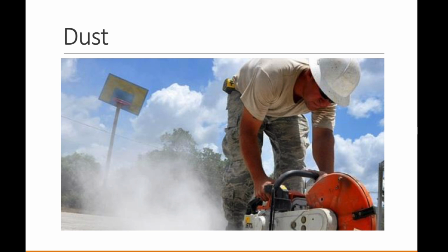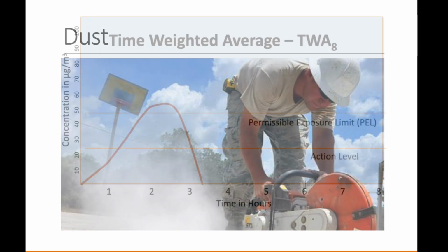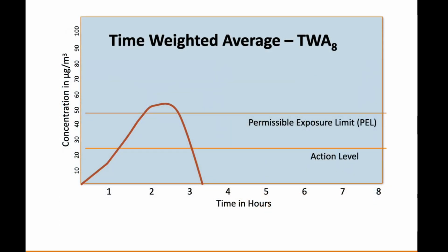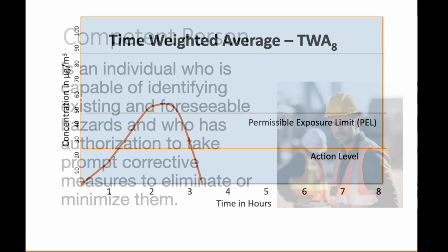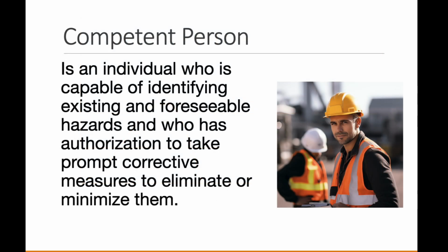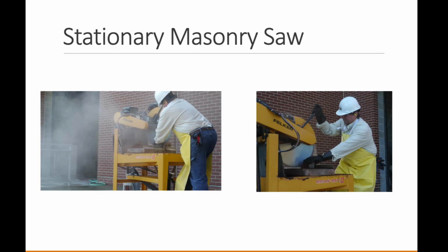So now let's talk about different applications. Dust from something like concrete sawing. Here we see the time-weighted average on a graph, and you can see the difference from the action level and permissible exposure limit. All jobs that have silica exposure must have a competent person.